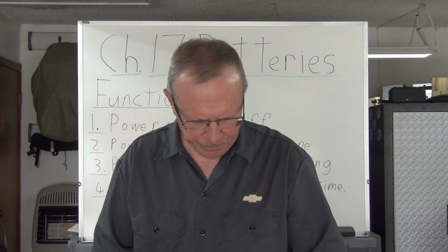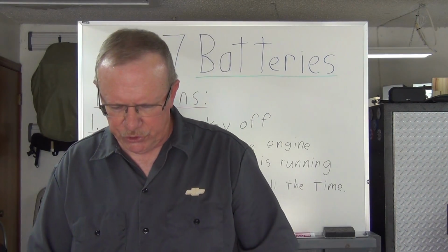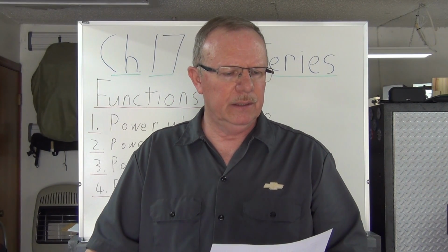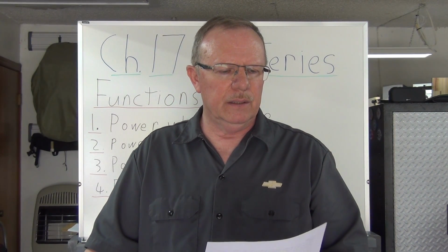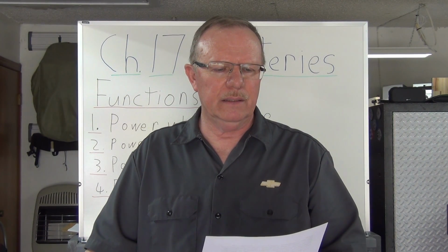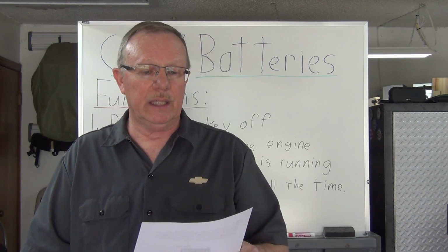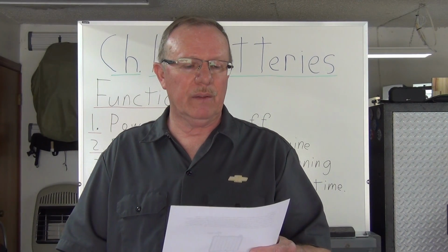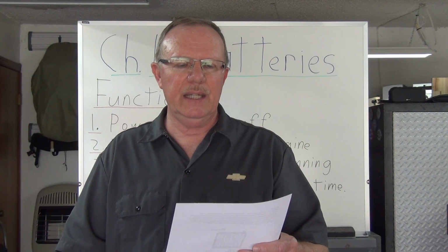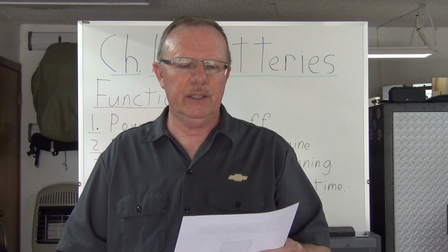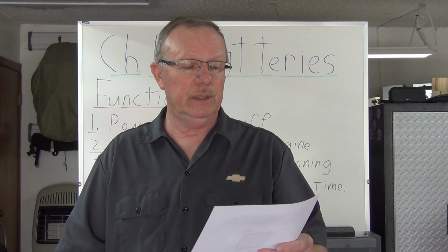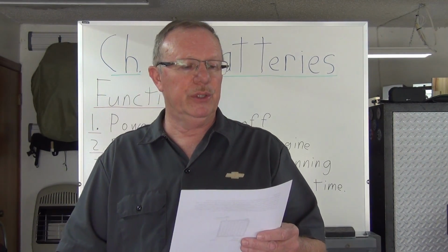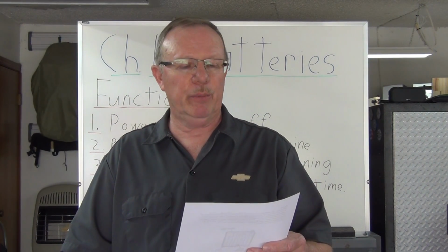All right. A little bit more about construction. The battery plates are constructed of a lead alloy, containing a percentage of either antimony or calcium. Okay, the plates are designed as a thin, flat grid, with grids crossing at right angles, shown in the picture there, or grids crossing diagonally in different angles, which reduces internal resistance. So they can be made a couple different ways.